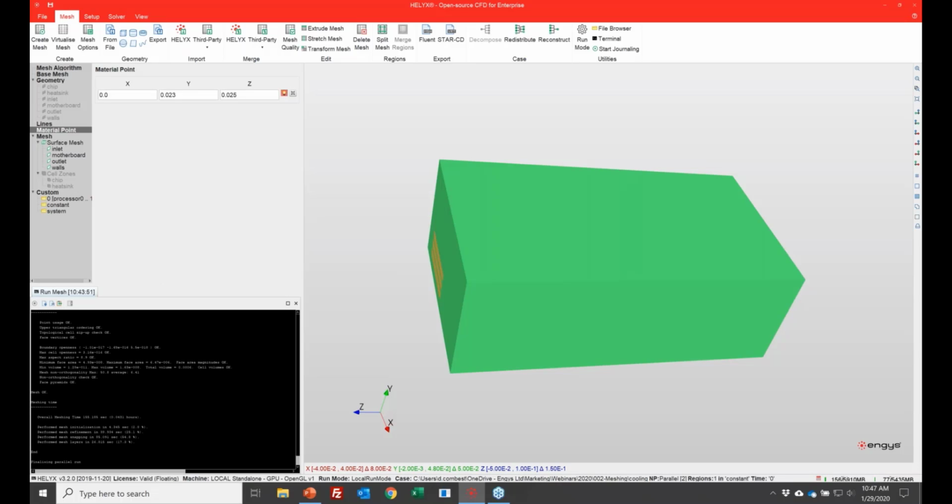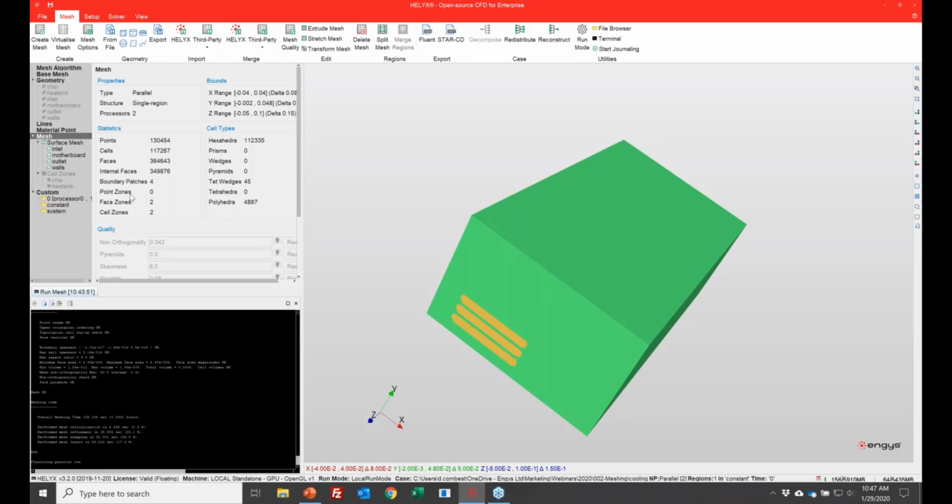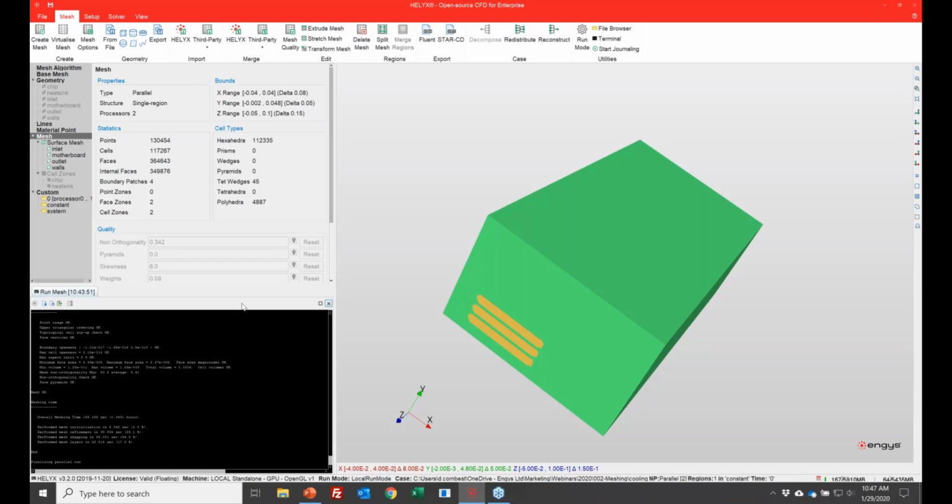Why would we need to minimize the number of faces between the processors? The lower the number of faces, the smaller the MPI messages are between each one of these processors. Okay, great. So that took a little bit longer than when I tested. However, this is fine. Let's go to mesh and let's see if we can visualize some of the layers.